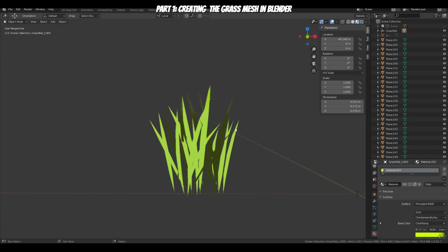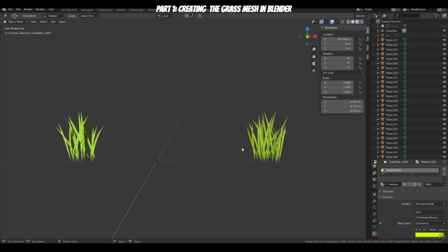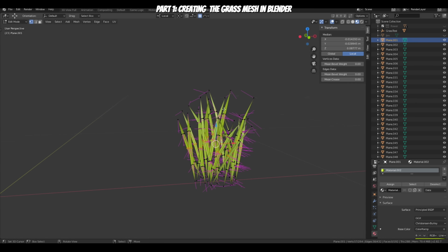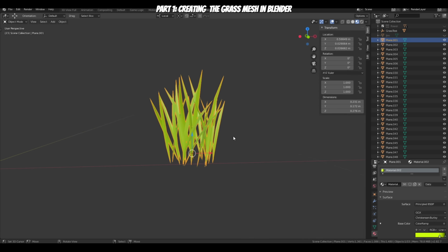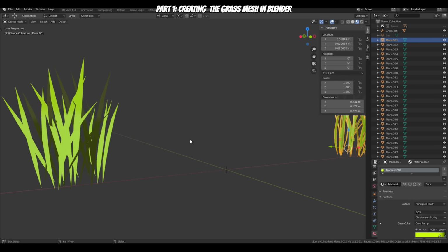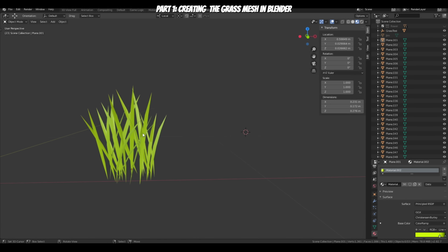And you can see the back faces are black. That's why we use the two-sided lighting fix on the engine. So this is an example of how it turned out before I edited the normals. And you can see that there's a difference in shading. This one's pretty flat, but this one has its shading still. And that's not what we want.